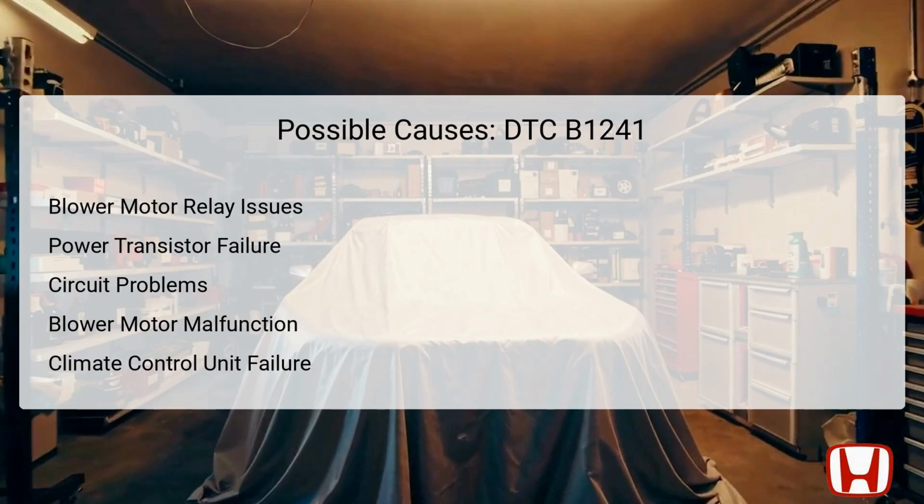The blower motor itself might fail due to wear and tear or internal failures, while a compromised climate control unit can misinterpret feedback signal voltages. It's crucial to systematically assess these components to determine the precise cause of the DTC.